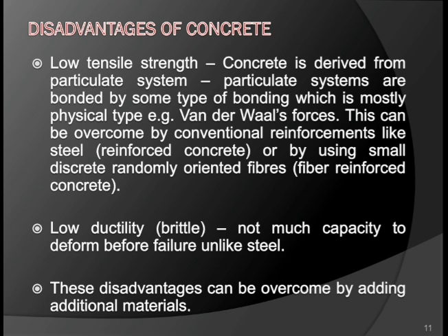So which are the disadvantages? First, as we know, low tensile strength. Again, this disadvantage can be eliminated by inserting steel reinforcement, right? Then low ductility. It is brittle, so not much capable to deform before failure, unlike steel. Again, this disadvantage can be eliminated by inserting steel.